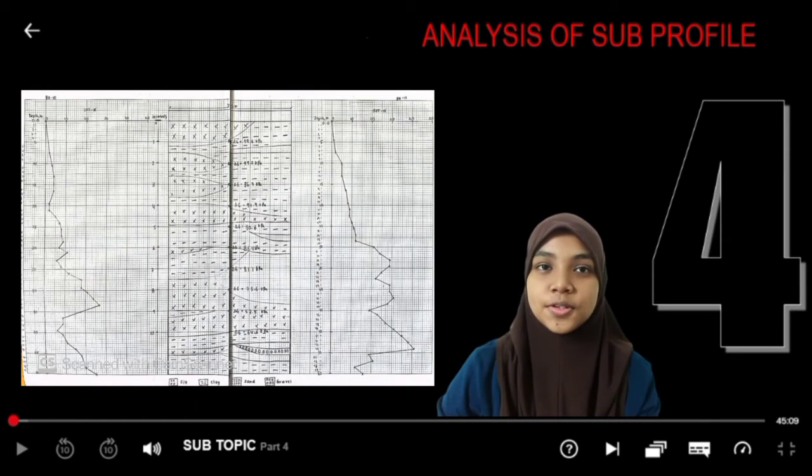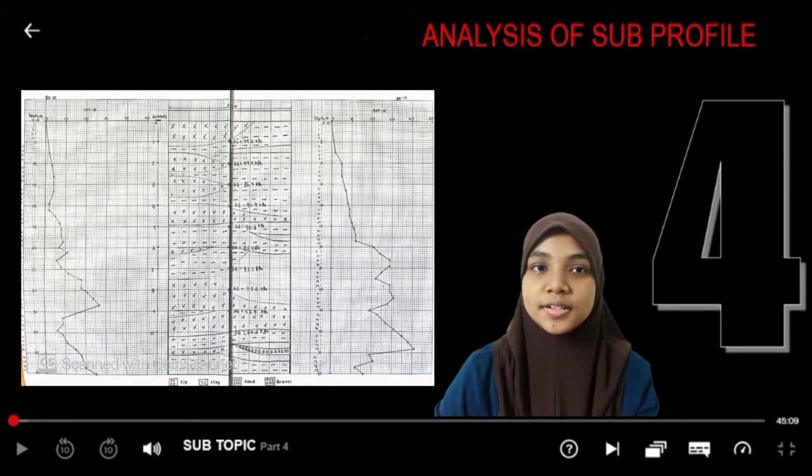Then, for the second borehole, the major types of soil are sand and gravel, which are coarse-grained soil. It has repeated layers of silty clay and clayey sand for the first 10 meter depth. They have a high bearing value which is most suited for foundation when effectively drained and contained.